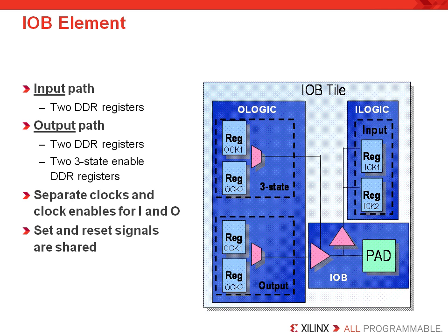To clock the DDR registers, remember that you can use any pair of the PLL or DCM outputs that are 180 degrees out of phase, such as the CLK90 and CLK270 outputs, likewise the CLK2X and CLK2X180 outputs, or even finally the CLKFX and CLKFX180 outputs.